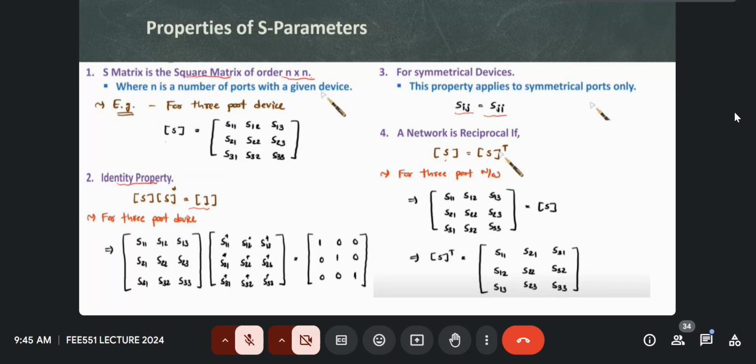So for example, if I input energy on this side of the network, port 1 for a two-port network, and I do the reverse, it should be the same. So S equals S transpose. Here, this is the S matrix. If you transpose this, of course, you take this and put it going like that. Take these S21, S22, S23, take that, go like that.